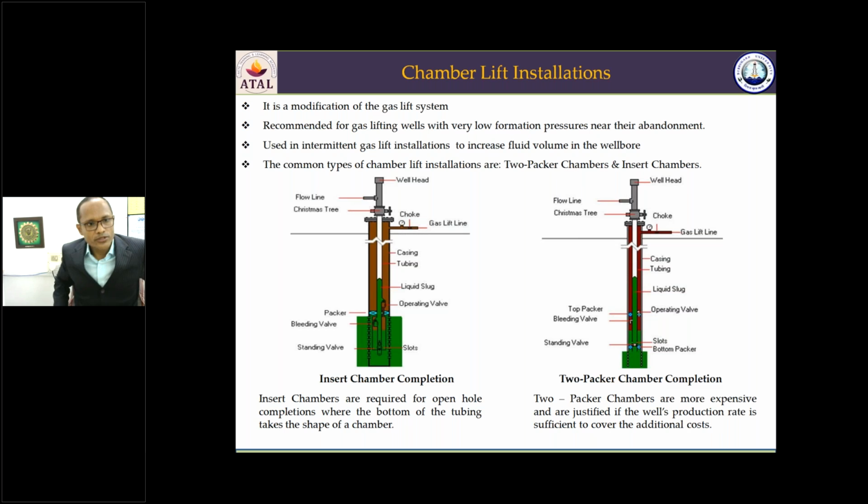So the chamber lift installation is a modification of the gas lift system. It is a gas lift system, only that the system is somewhat modified. It is recommended in gas lift wells with very low formation pressure. When the formation pressure is very low, that is, when the BHP, the bottom hole pressure, is very low, this type of gas lift system is used, chamber lift.